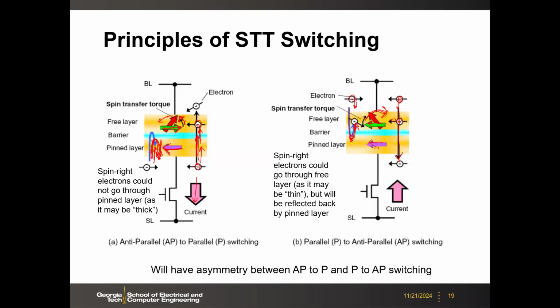That means, as I said earlier, you have that complex structure to stabilize the pinned layer, which is thick, and with the help of this synthetic antiferro layer, then it's pinned. Or in other words, in real operation, your current is not large enough to trigger that change. Of course, if you have a very large current, or you put it under a strong external magnetic field, like tens of Tesla, then of course you will destroy everything. In normal operation, it is pinned.